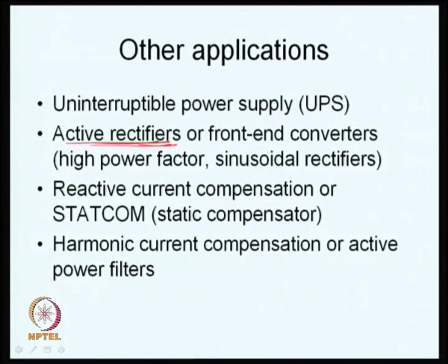Here rectification, that is AC to DC conversion, is done, but unlike a diode bridge rectifier, an active rectifier draws near sinusoidal currents at a fairly high power factor, something close to unity. Again, as I mentioned before, a voltage source converter can be used to compensate reactive current. If other loads are drawing a lot of reactive current, you can have a voltage source converter that supplies part or most of this reactive current, and that is called a STATCOM or static compensator.